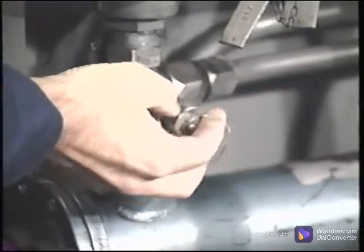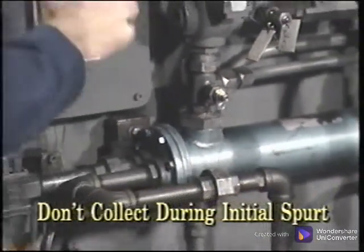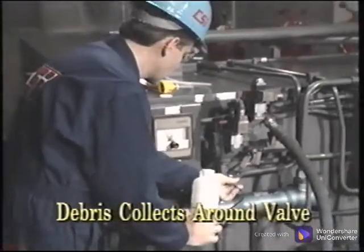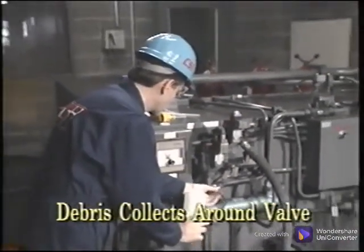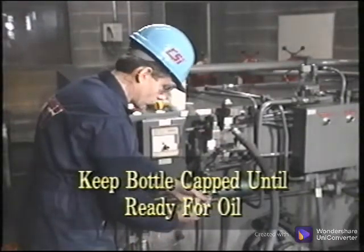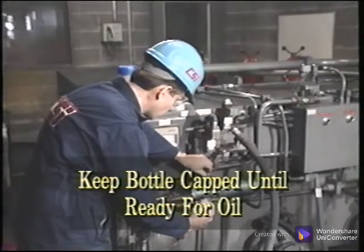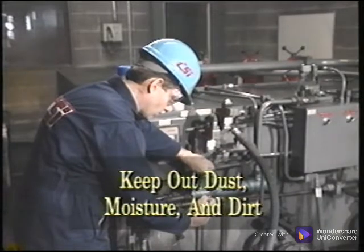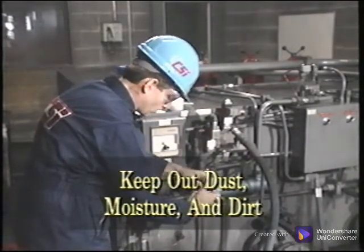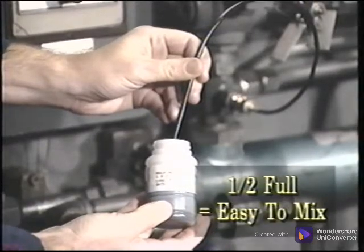When drawing oil through a drain plug or valve, don't collect oil during the initial spurt or rush. It may contain metal from the plug threads, and it will certainly contain debris that is collected over time around the plug or valve opening. Don't take the cap off the clean sample bottle until you are ready to take the sample. As soon as the sample is taken, replace the cap. This will help to keep the dust, moisture, and dirt out of your sample. Fill the bottle about half full. This makes it easy to completely mix the sample by shaking prior to testing.